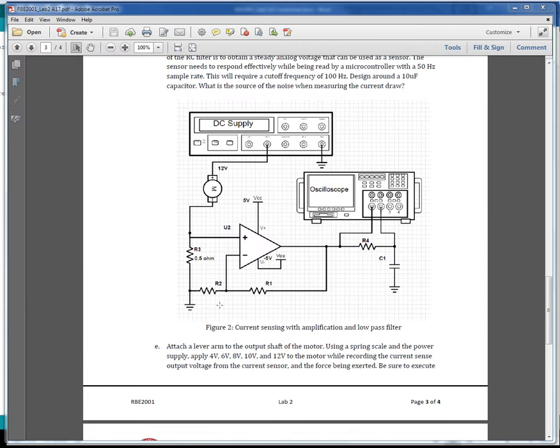So that means that if we have low voltages coming in here, even with the gain, it's still going to be pretty low. And so we actually have to have a negative voltage. And the TAs and SAs can show you how to hook up the power supplies so that you can actually have -5 volts to +5 volts on the rails.